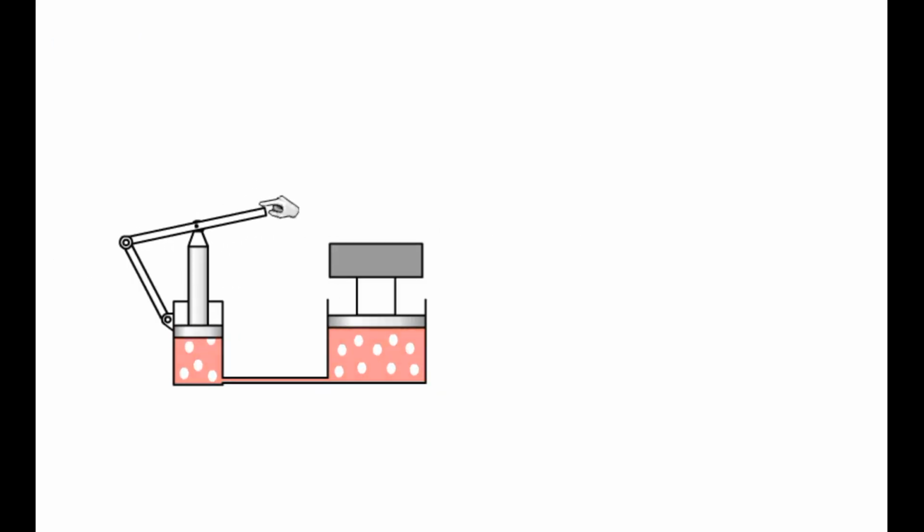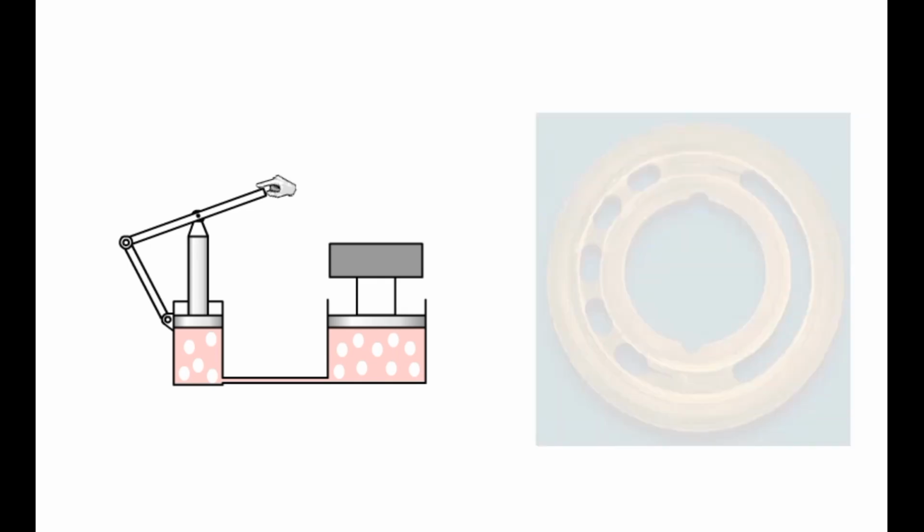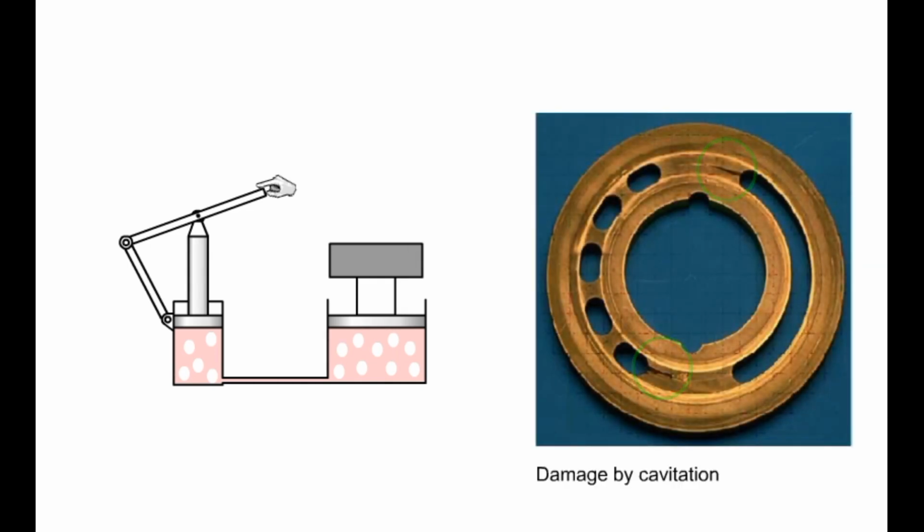It is desirable that the hydraulic fluid in a hydraulic system should not contain air. Air is extremely compressible and thereby impedes the function of a hydraulic system. Also, air bubbles that have entered the system can, under cavitation, cause considerable damage, for example in the hydraulic pump. In order to remove air from the hydraulic system, bleeding options are normally provided in the cylinders. A number of constructions have been created to simplify this process. In the following screen, we will look at the Rexroth patented air bleeding system.